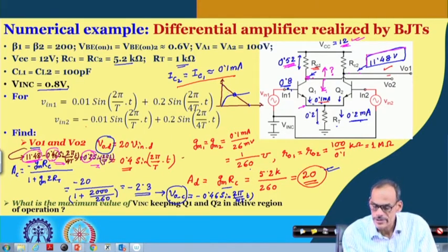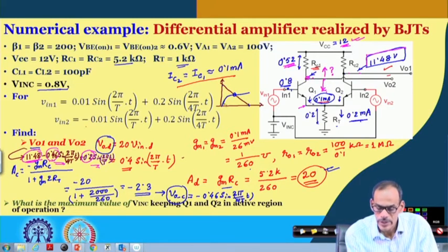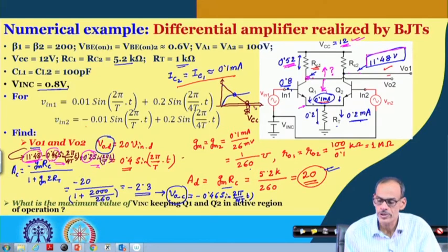Now, in this case, since the current here is too small, the corresponding characteristic curve of the transistor is here. So, due to the small current, the operating point is very close to that VCC supply. As a result, even if we do have a small signal, the signal is getting distorted there. So, we need to be careful there.